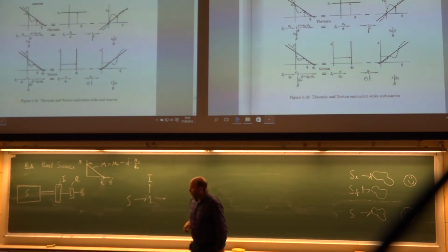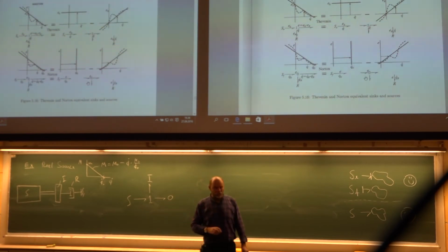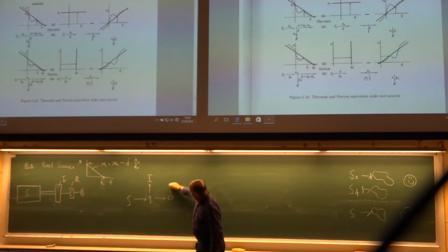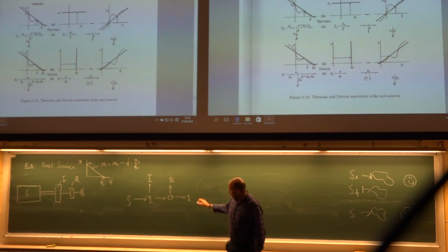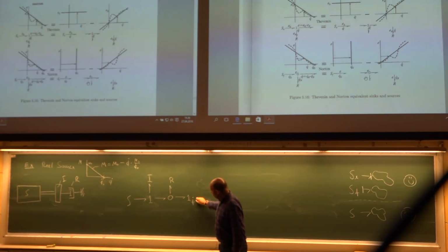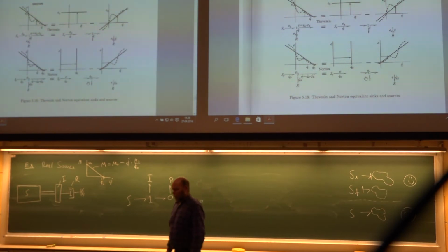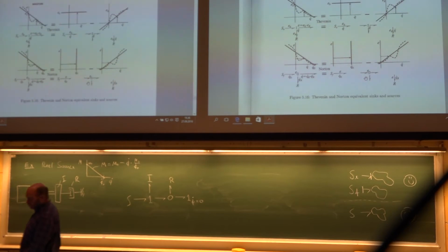Continuing, I hit a resistance. A resistance we insert with a 0 junction. You have the same torque on each side of it. So here is the resistance, and then we continue into another 1 junction. That's a solid wall. It is not rotating at all. Phi dot is 0. So there you have the raw bond graph.